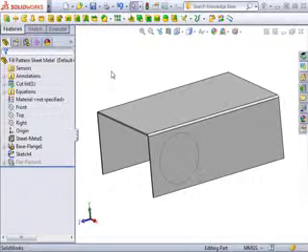There are two basic elements for a fill pattern: a feature to serve as the seed for the pattern, and an area to fill with the seed feature. The seed feature can either be a pre-existing feature or one of 4 shapes available in the Fill Pattern Property Manager. The area can be defined by a flat face, a sketch, or a curve on a flat face.